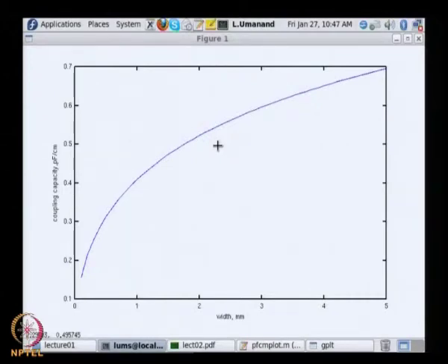So, therefore, when you want to have ground and supply lines, let us say one layer is the supply line and another layer is the ground line, you try to make the coupling capacity as much as possible, so that you get more capacitance or lesser impedance between the supply and the ground, so that they are able to give much more value of spike currents when the digital circuits go through transitions.